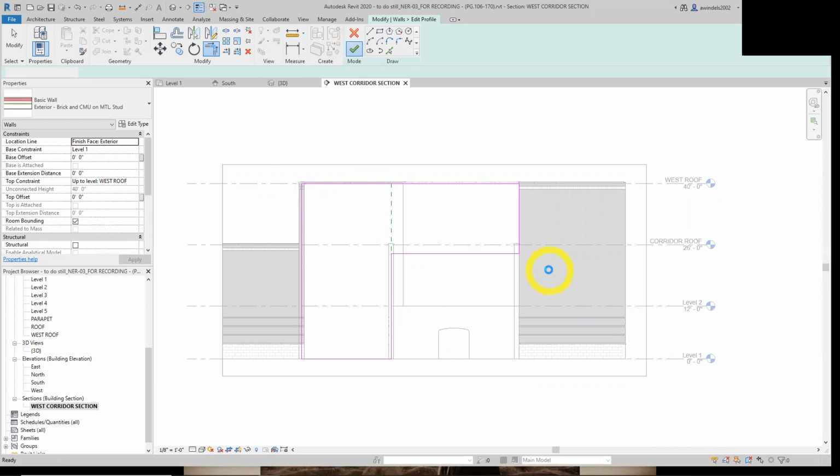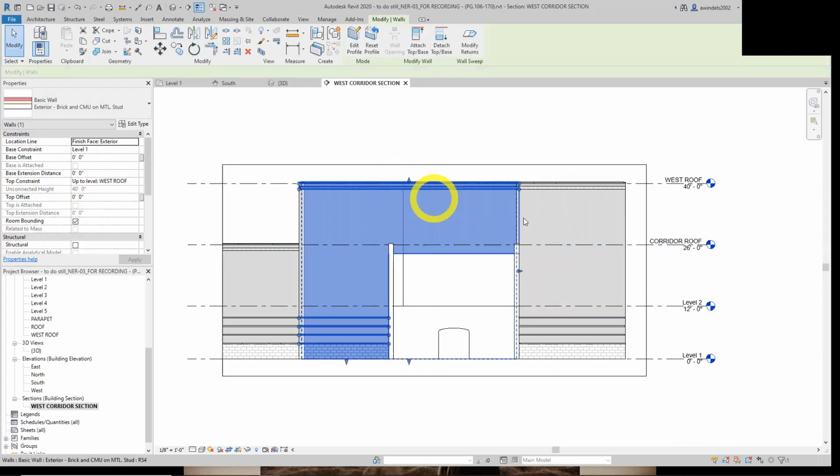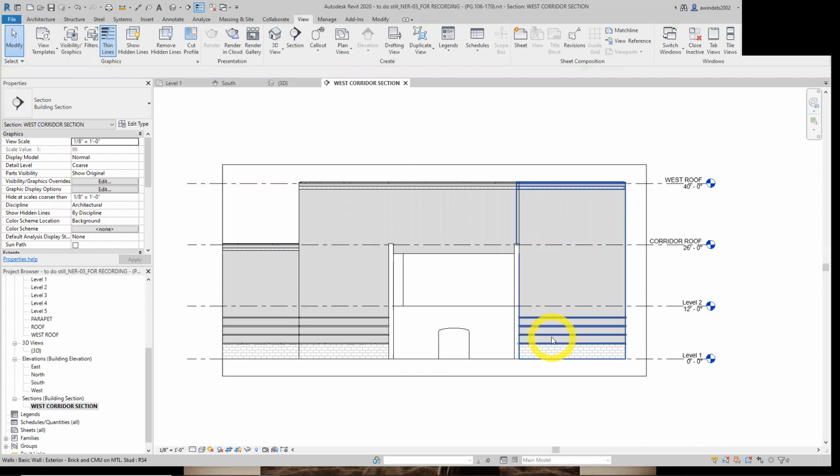Finish edit mode. Finish profile there. Now we filled in our wall. Okay. If you don't have a perfectly closed continuous loop with your magenta lines, Revit won't allow you to proceed to finish altering the profile of the wall, so make sure you have no gaps, overlaps, or extra line segments from the 6 lines. That's easy to get hung up on, and I had it happen my first go. So we edited the wall, and let's see what else we need to do.